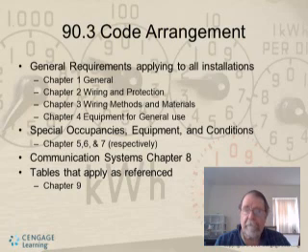that apply as referenced. In other words, you will be going to those tables to look information up, to do calculations for load calculations, for figuring out the amount of conductors that would be required, or you have a certain dimension of a box and you want to make sure that you're legally able to put in the conductors that are going to feed through that system. If not, then you have to mount a bigger box, things like that.